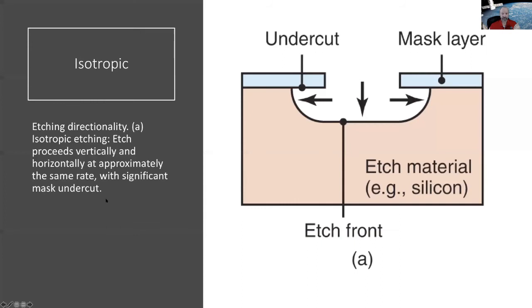All right. So we can do different kinds of etches. A mask material, the material protecting what's underneath, can be photoresist, like we talked about, but it could also be a patterned layer like a silicon dioxide layer or silicon nitride layer. And then you have openings.